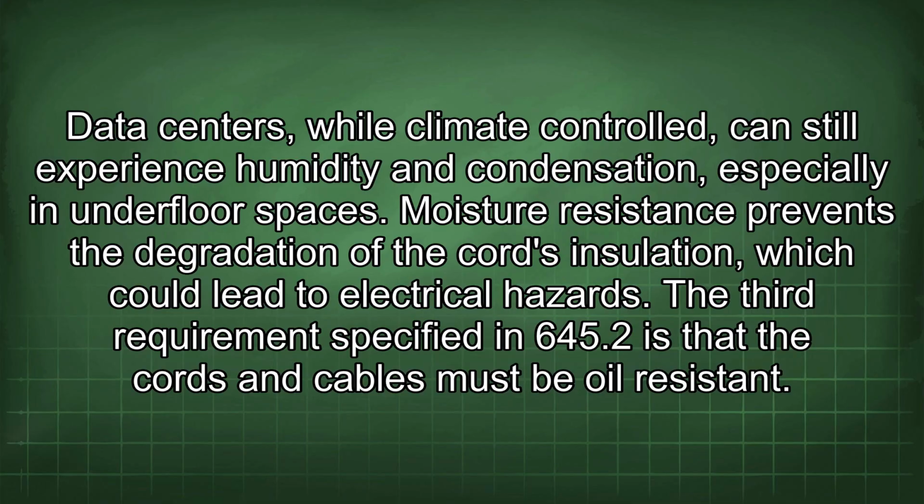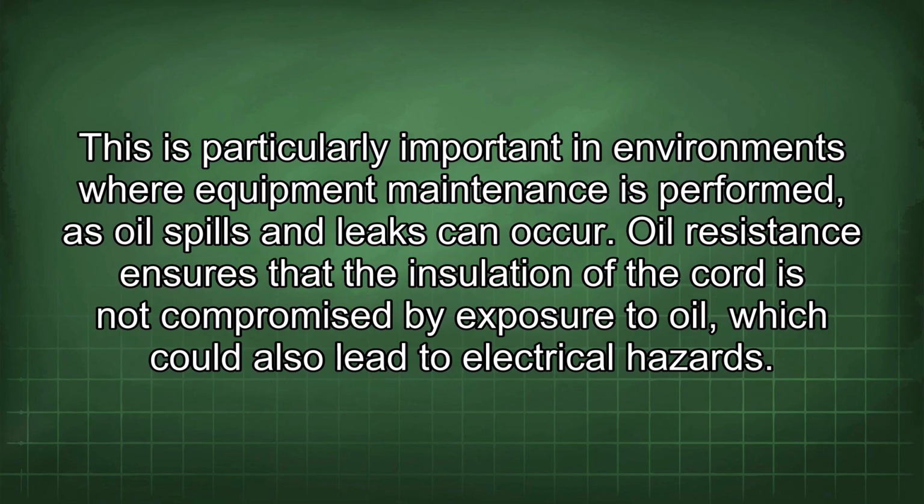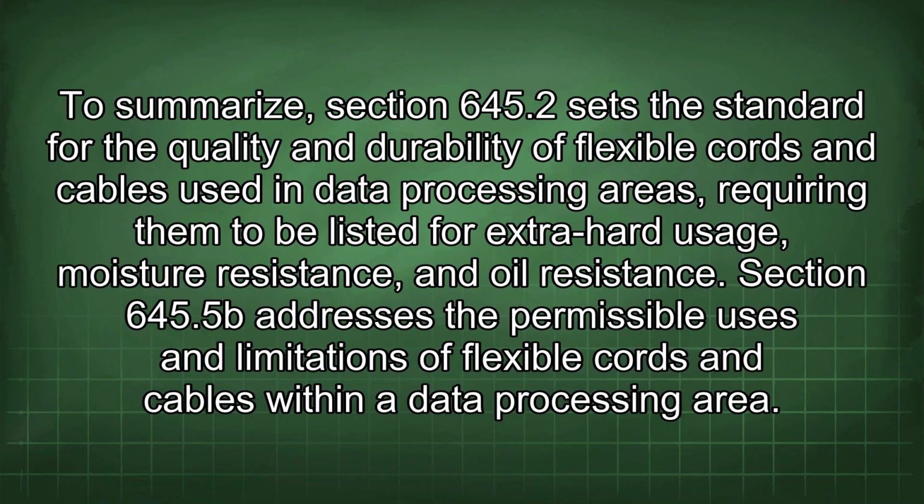The third requirement specified in 645.2 is that the cords and cables must be oil-resistant. This is particularly important in environments where equipment maintenance is performed, as oil spills and leaks can occur. Oil resistance ensures that the insulation of the cord is not compromised by exposure to oil, which could also lead to electrical hazards. To summarize, Section 645.2 sets the standard for the quality and durability of flexible cords and cables used in data processing areas, requiring them to be listed for extra hard usage, moisture resistance, and oil resistance.